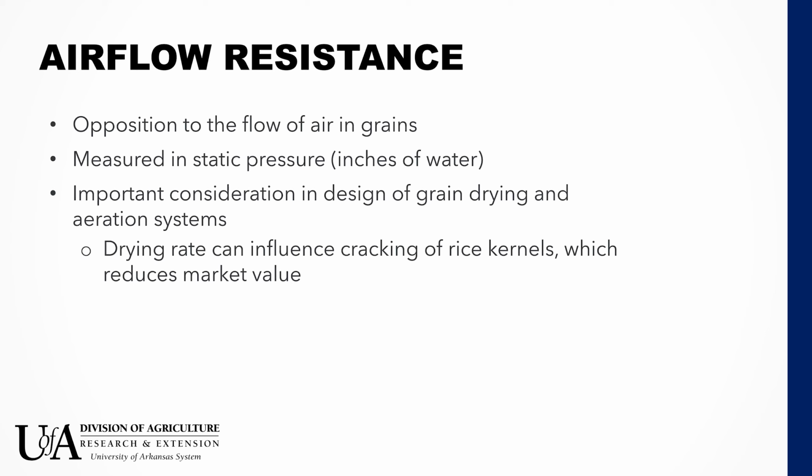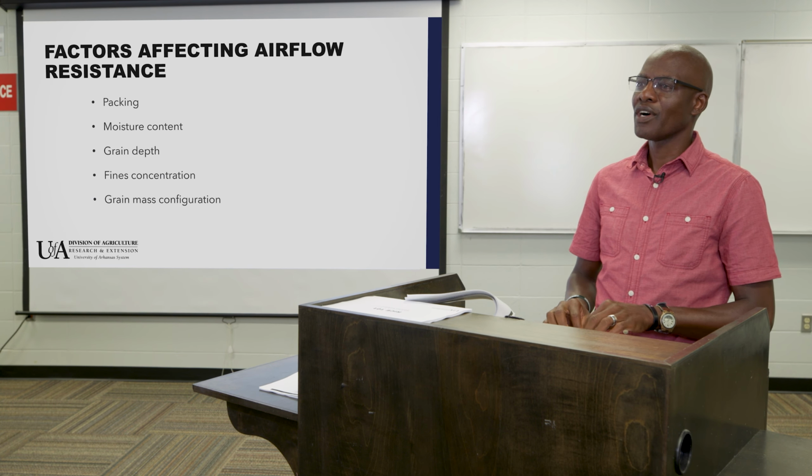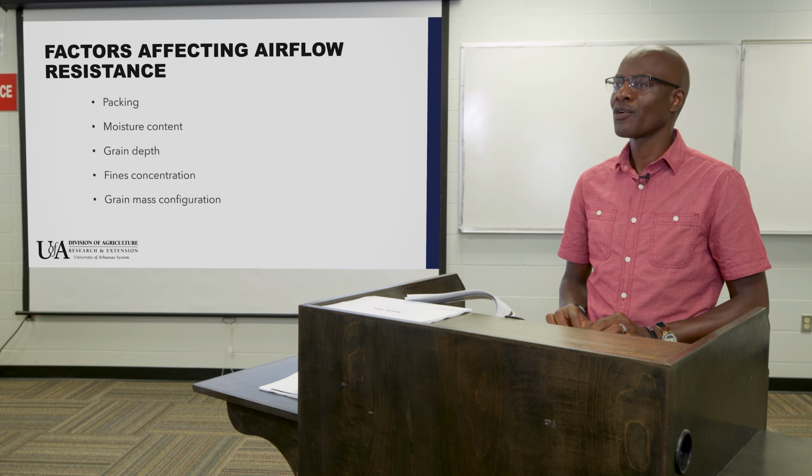And the amount of air that you push through the grain will obviously influence its drying rate. For rice, that's very important because the rate at which that rice dries will influence things like fissure formation, and if that is not done right, it may reduce the market value of that rice because it impacts the head rice yield.